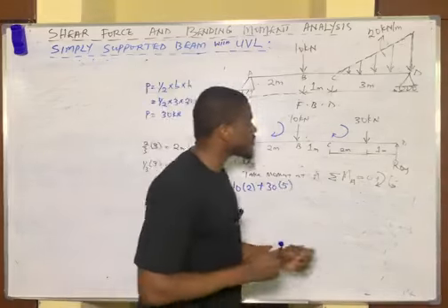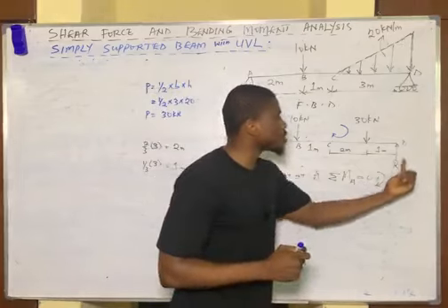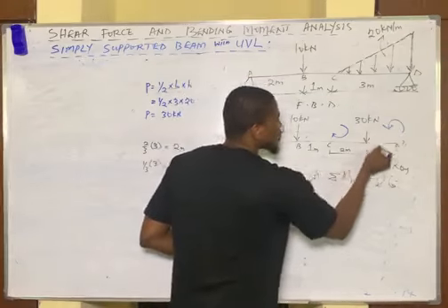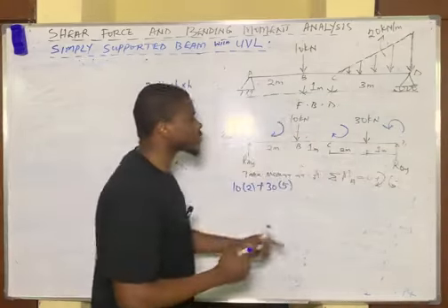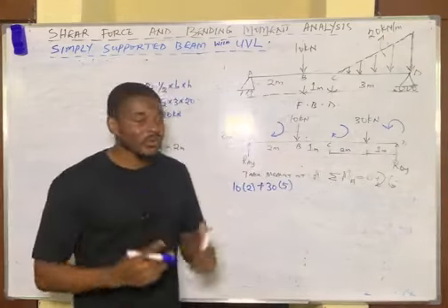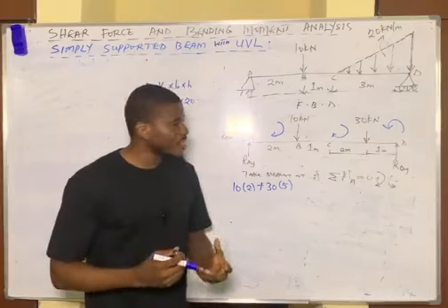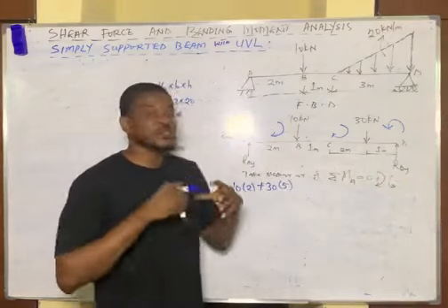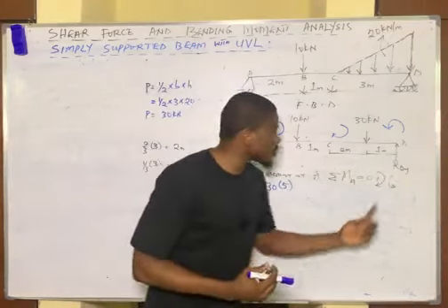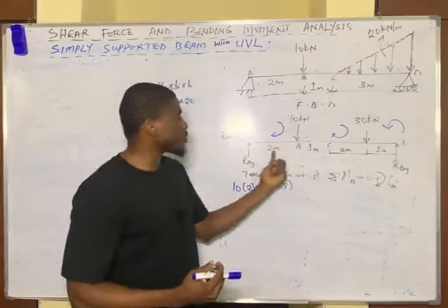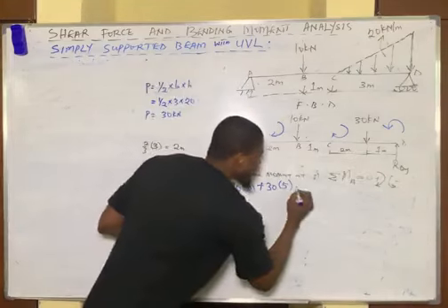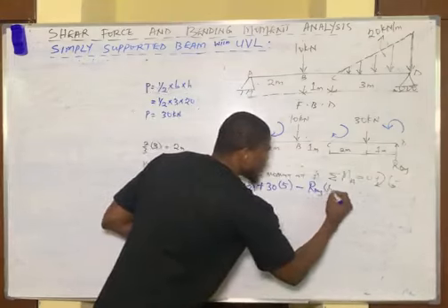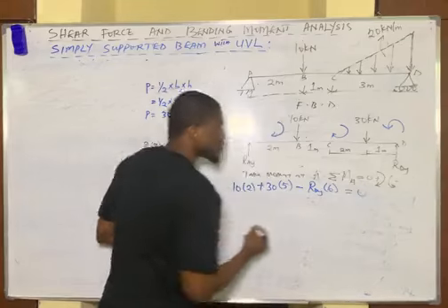Finally, you have the RDY pointing upwards. That means this force will turn about in this direction to take moment at point A. And that direction is anti-clockwise. And anti-clockwise, we say, should be what? Negative. Total distance it takes this RDY force to get to point A becomes the total length of the beam, which is simply what? 3 plus 1, 4 plus 2, 6. So you simply have minus, because it's anti-clockwise, RDY multiplied by 6, and this is equal to 0.